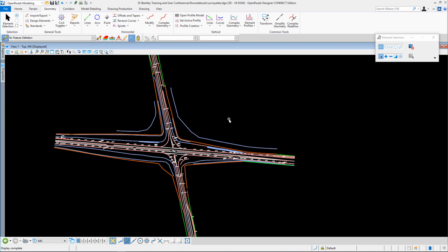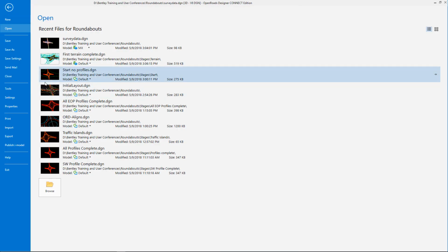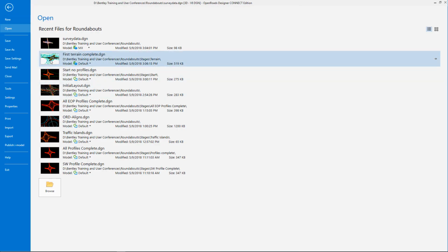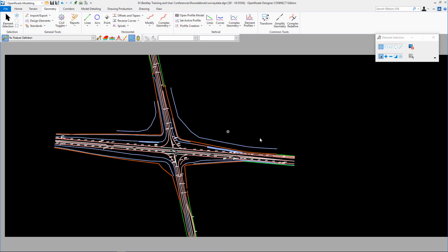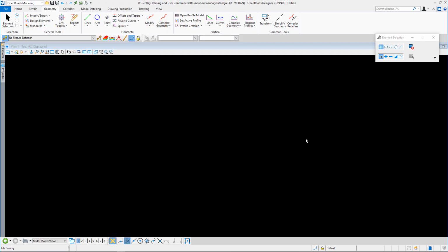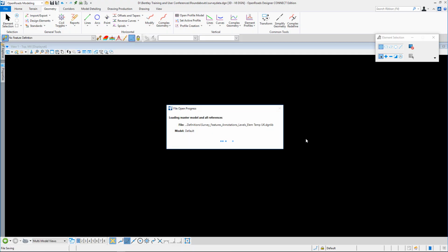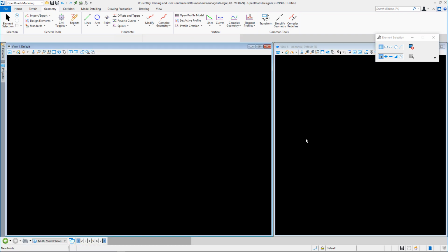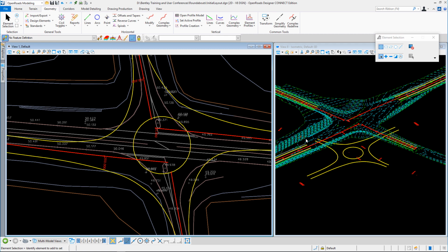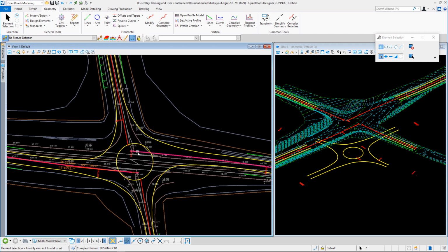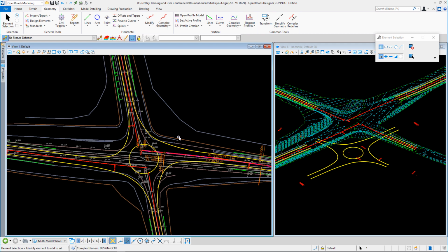And of course, we then need to develop our horizontal geometries for the whole of the roundabout. Again, we're making assumptions that analytical software, something like Arcady in the UK perhaps, has been used, which will give us the new geometry, the deflections and so on, so that we can fit in a roundabout here.